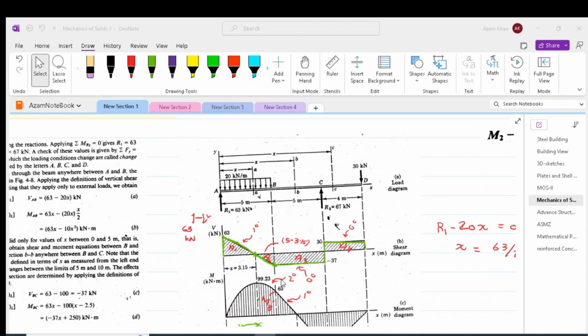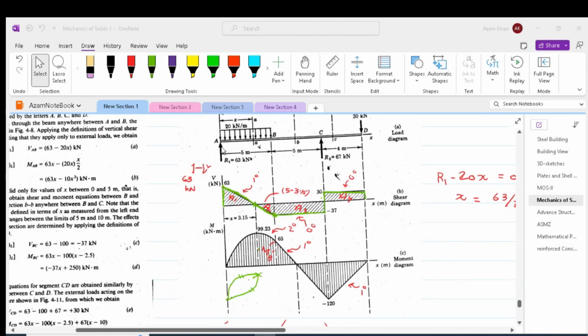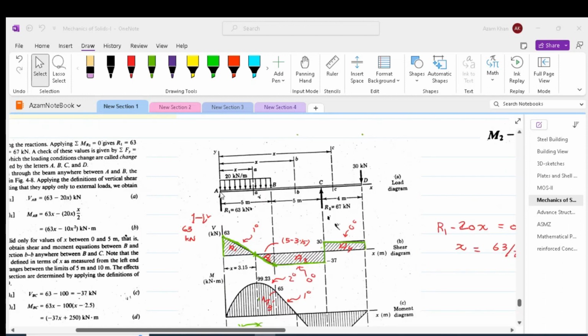First thing to appreciate is that the bending moment diagram will be 1 degree up to the shear force diagram. So between AB, the bending moment diagram would be of 2nd degree. In other words, it would be parabolic. Since A is a simple support, therefore the bending moment diagram should start from 0. As we discussed, if the shear between any two reactions is 0, then at that point we would have a maximum moment. So at the point of 0 shear, we would expect maximum moment.